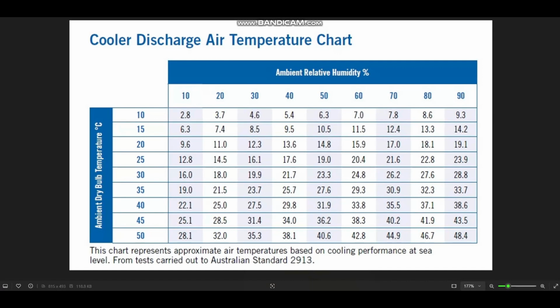It depends on how well insulated the flexible ducting is, how long are the duct runs, how many bends and turns are there in the duct, and how well insulated the roof is. So you could pick up anywhere from 0.5 to another 2 degrees Celsius, which means that the temperature at your ceiling, your delivery point, the grill inside the ceiling, could be between 20.5 and 22 degrees Celsius. From there, the air needs to displace the heat energy inside the room and push it out through open doors and windows. This process, again, you could pick up another 1 to 2 degrees Celsius.